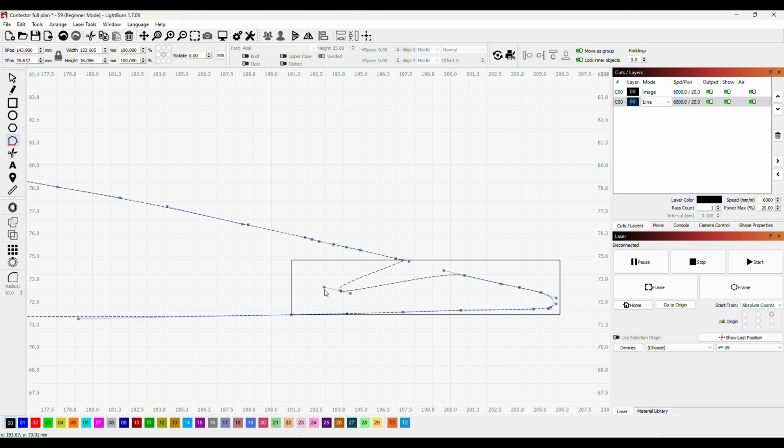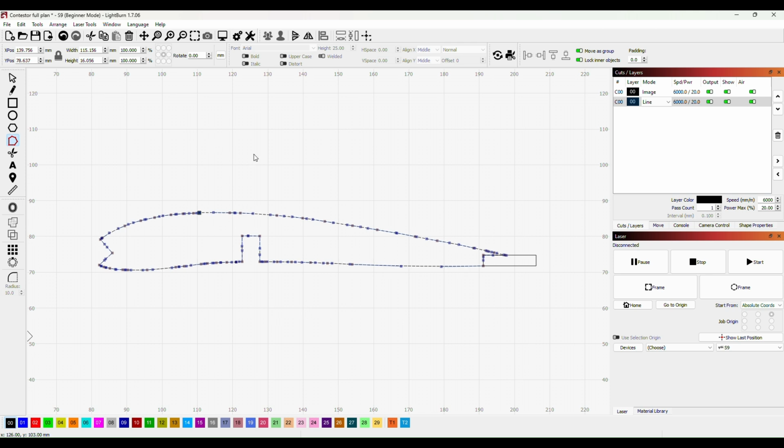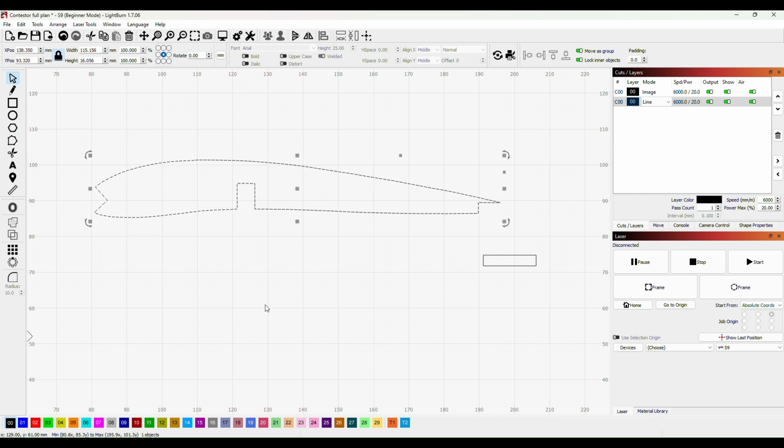And now what I can do is take onto there, and then remove these by highlighting them all, and then press D, and then bring this up. And what we'll find now is my trailing edge will be sanded down to a nice taper, and the formers in the wing, the aerofoil profile, will sit right on top of that trailing edge, just like that. So that's how I'm going to do those.